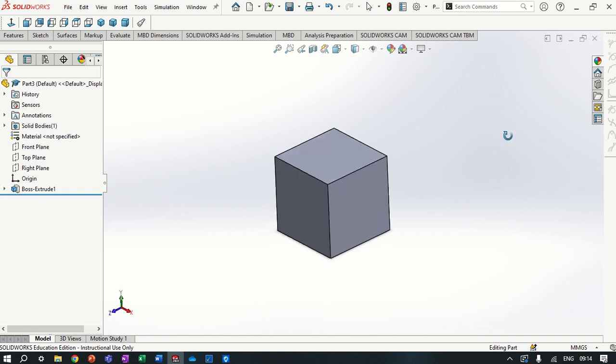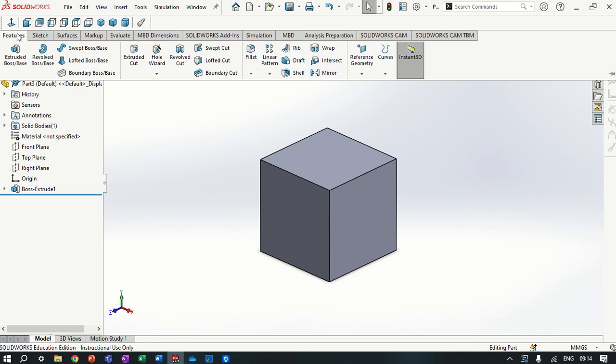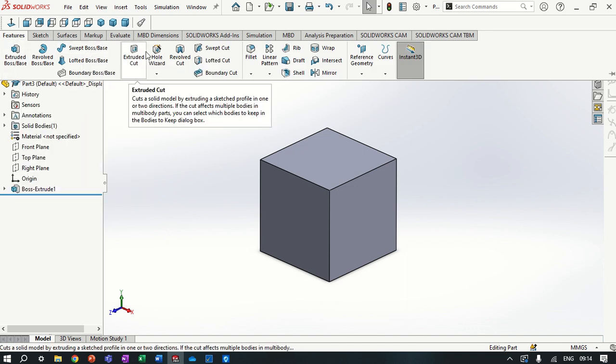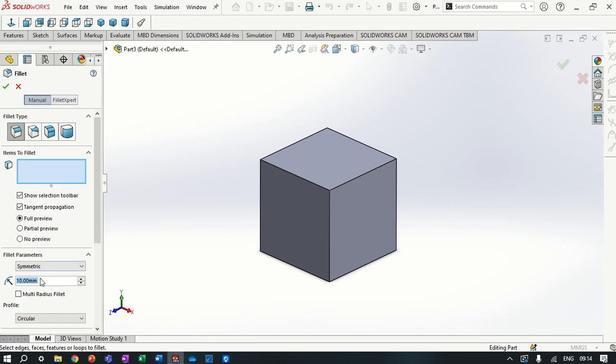Shadows on it, yeah. I'll do one more thing, okay? I'm going to use another thing called... how many minutes is this video? 15. One quick thing, we're going to round the corners or the edges on the cube, soften them up. So we go to features, and we've done extrude. We go over here to fillet. So fillet is when we round the corner. So click fillet. Down here, I'm going to make it a 5mm radius fillet.